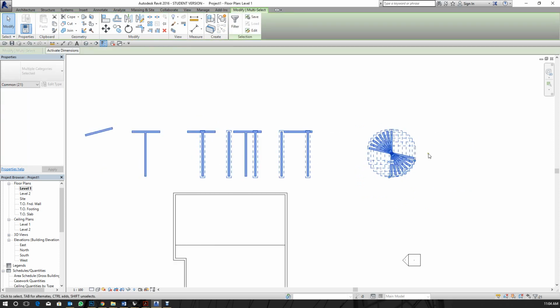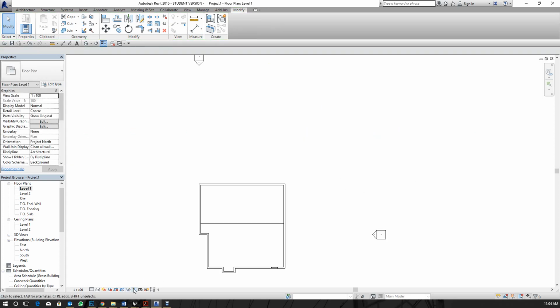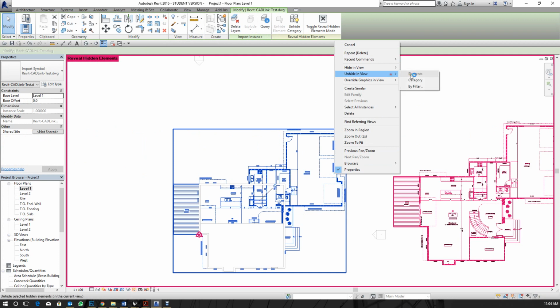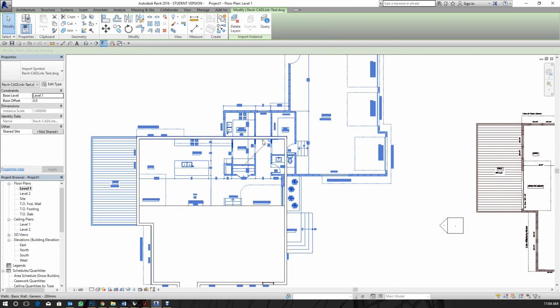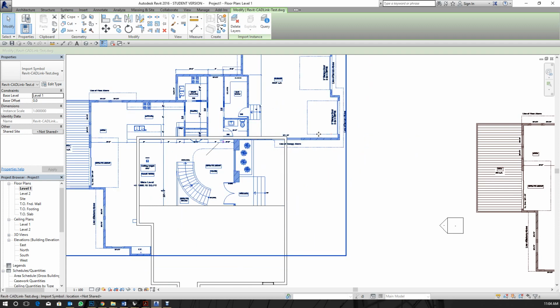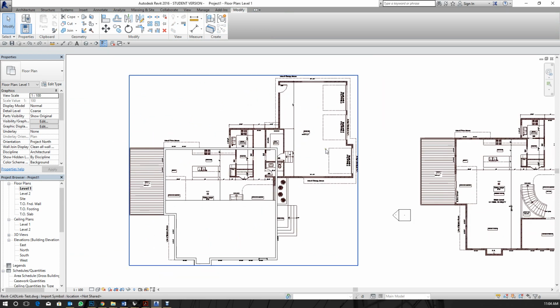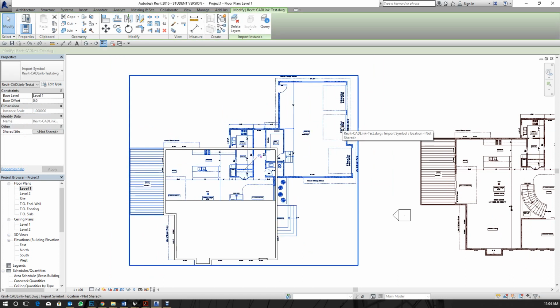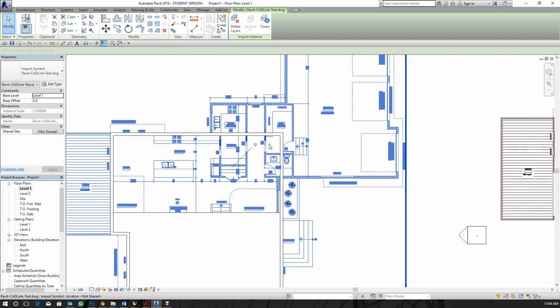Okay, now there is a pin and unpin. So for instance, I'm gonna go ahead and unhide this drawing again, a famous drawing. Now if I was drawing my walls over this CAD import, and for some reason I clicked on it and it moved, I could easily undo it, but if I had done it multiple times, it could sort of mess things up. So in order to avoid that, you can select that drawing that you have imported, and in that menu, you will see a pin, and you can just click that icon and it pins it.